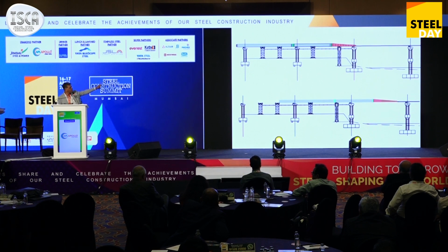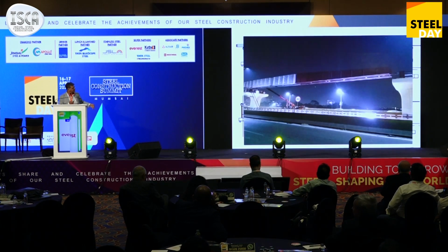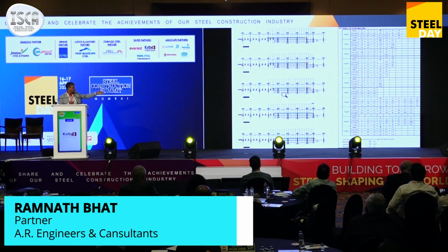First, we assembled two girders, and that green portion is a temporary splice. The bridge is designed as simply supported, but for launching we want a continuous structure. The red one is the launching nose. It is called a cantilever nose because it makes the cantilever arm lesser, safe for bending moment. You can see here this girder being launched onto the further pier. So these are the stages.